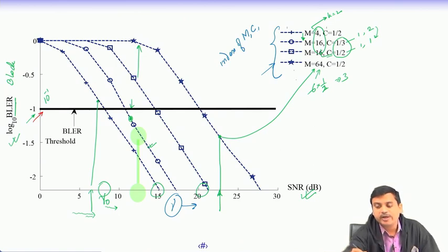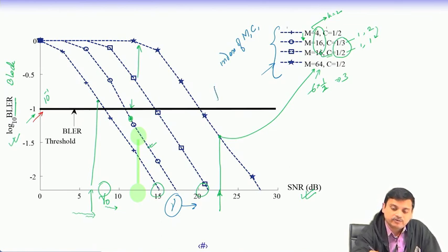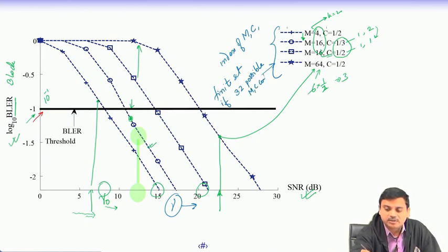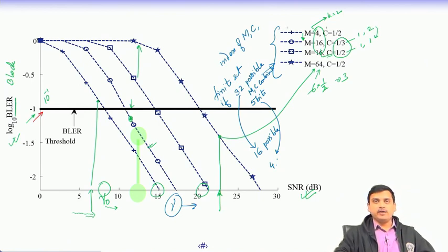Otherwise, we can have various different modulation and code rates, but there is only a finite set. So, let us say there are 32 possible MCS combinations, then one will require 5 bits to identify them, and this is sometimes reduced by choosing 16 possible combinations, and hence you reduce to 4 bits. That means every signaling will have 1 bit less.